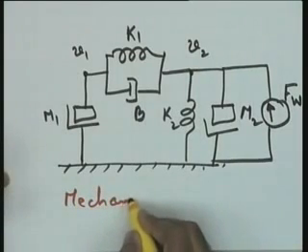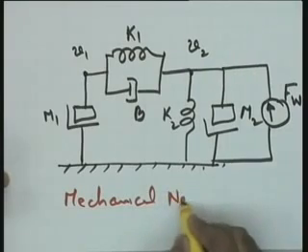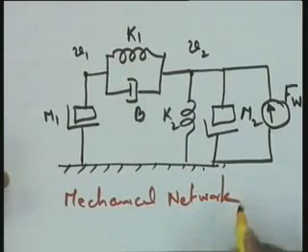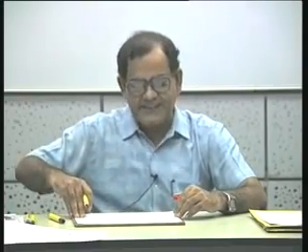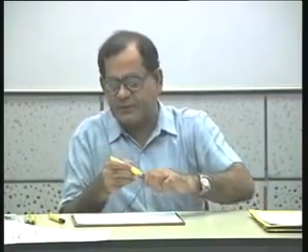And if you appreciate this change, in that particular case equations can directly be written in terms of the mechanical network rather than converting them into resistance, capacitance, inductance and current elements. We can directly write the equations. Instead of the current balance, now you will have the force balance, current being analogous to force. In that particular case, help me write the equation at node 1. I will write the equation and you can compare whether it tallies with your equation.